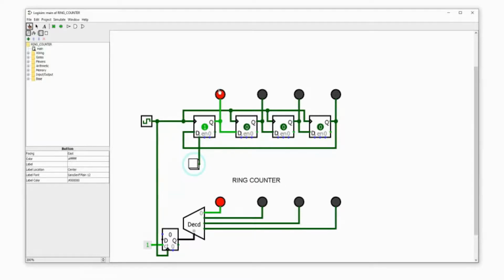It will just travel from this point to this point, and then this point to this point, and then this point to the next, so it will be traveling towards the right and coming back to the first point again. So this will be your ring counter. It is moving in a circle, or moving in a ring. Okay, so can you see that it has moved in one clock pulse?